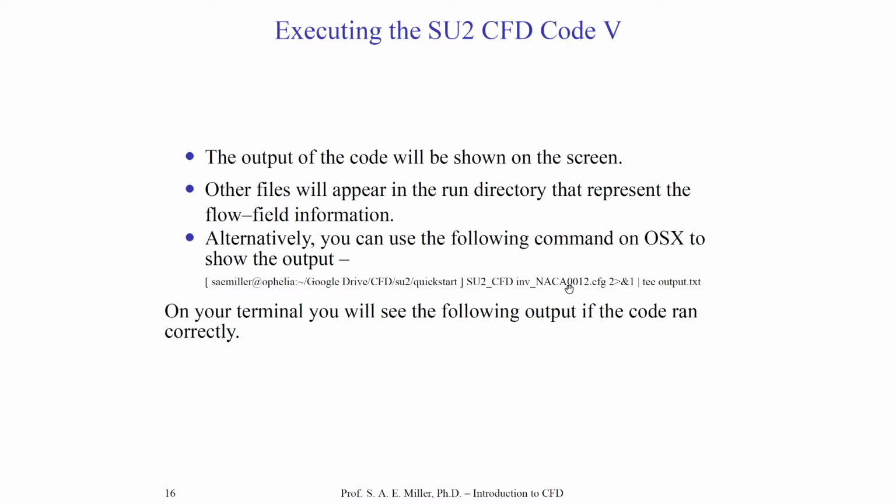I could call it, say, chicken.cfg. So I could write SU2_CFD chicken.cfg. And it'll read that file. But it's better to always name it something that makes sense. Now, this is the required part of the command to run and execute the code. And some cases will take a long time, so be patient. And you'll be running this code a lot of times during the semester, so it's good to get used to this now.